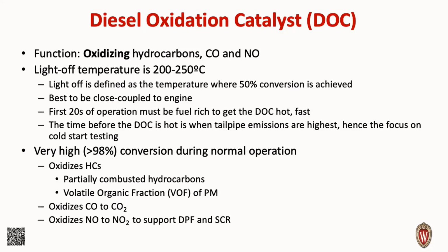And the time before the DOC is hot is when tailpipe emissions are the highest, and that's why we tend to focus on cold start testing for emissions reasons, like for EPA compliance. Once it is at its normal operating temperatures, we see very high conversions, better than 98%. So again, it oxidizes the partially combusted hydrocarbons from the fuel or any of the VOF off the particulate matter. It oxidizes the CO to CO2, and it oxidizes the NO to NO2, which will be useful to the DPF and SCR.